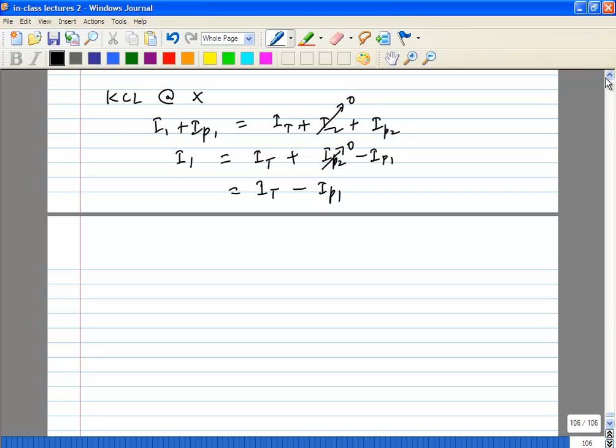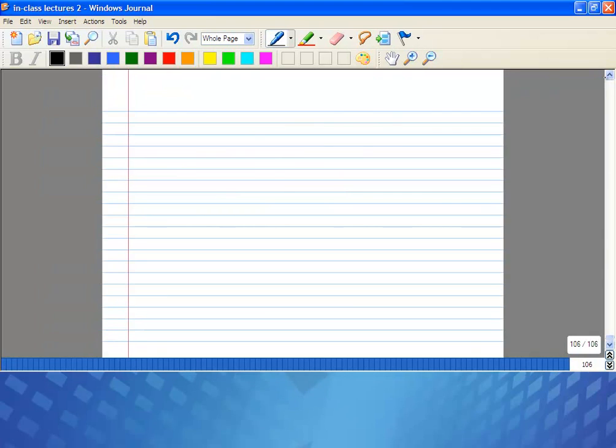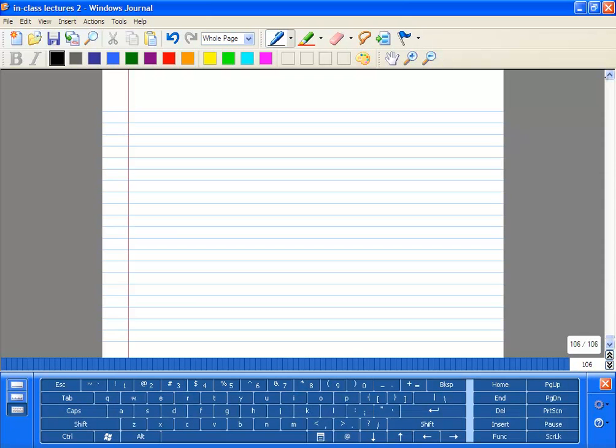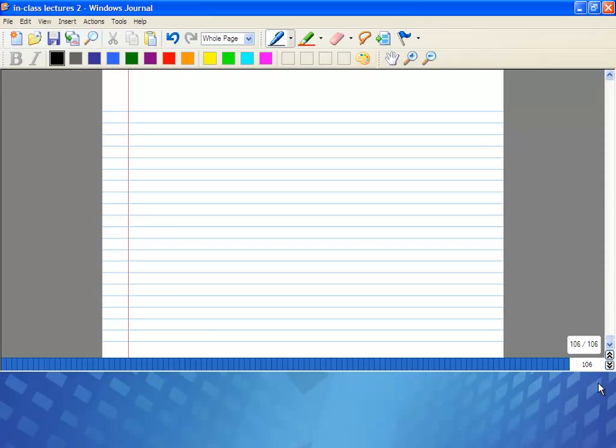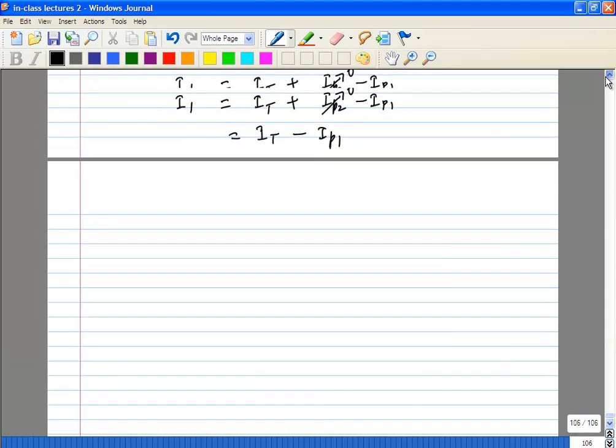The change in voltage across each is the same, but the capacitance is very small, therefore you can assume that the current is very small, because it's just the overlap capacitance. So what we are actually doing is neglecting IP2 with respect to IP1, not randomly neglecting IP2.